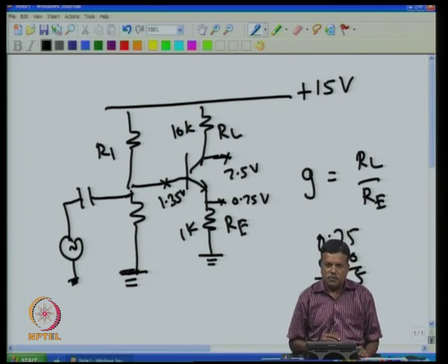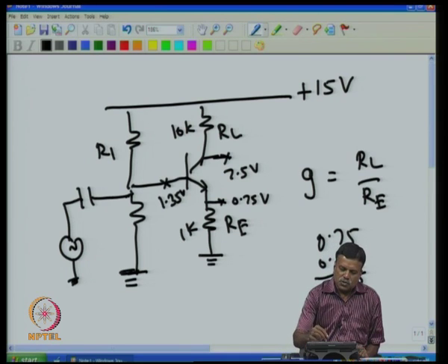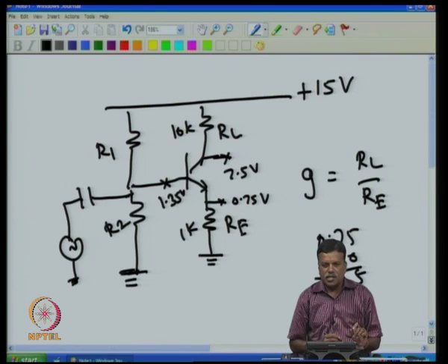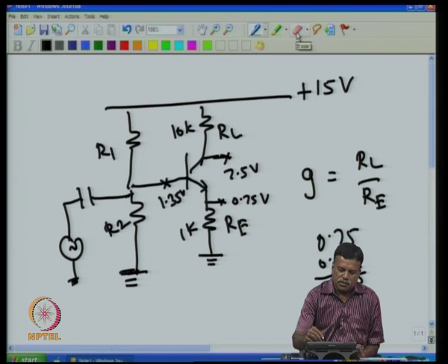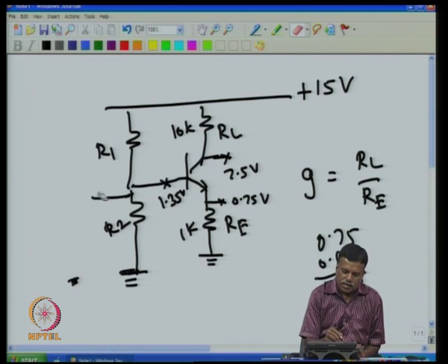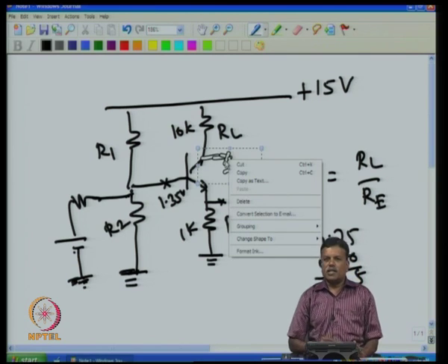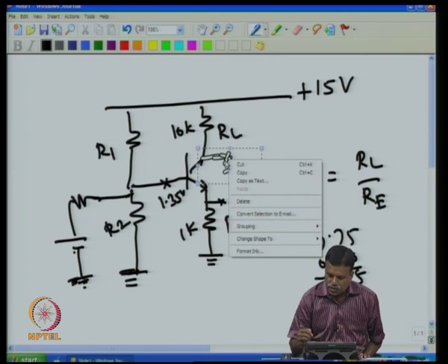Now, this is a very simple amplifier, but nevertheless there are issues in this. It does a good job amplifying AC voltage, but if I want to amplify DC voltage, then we get into problems. For example, one way of doing this would be to apply a DC voltage here, and then this voltage change will produce a DC voltage change here, which will produce a DC voltage change here. Like this we can use this to amplify the DC voltage.